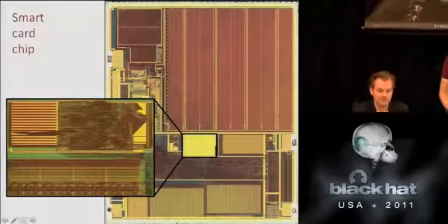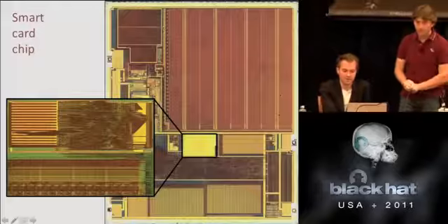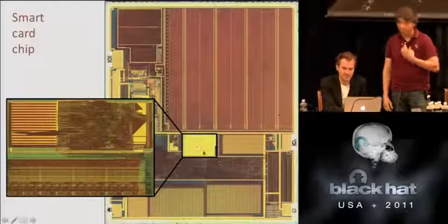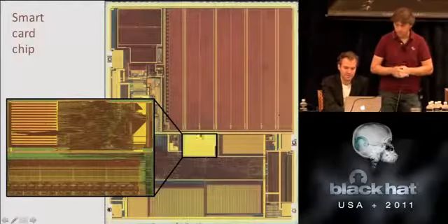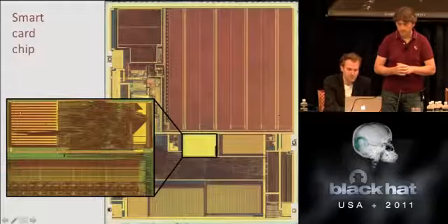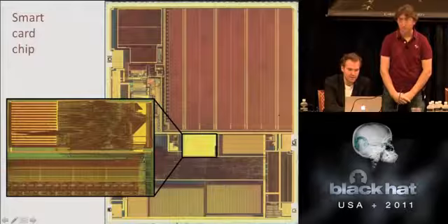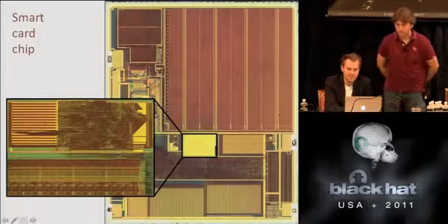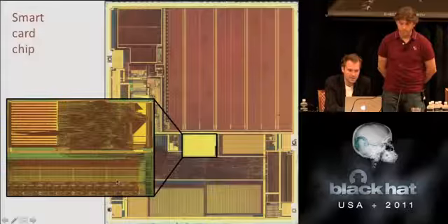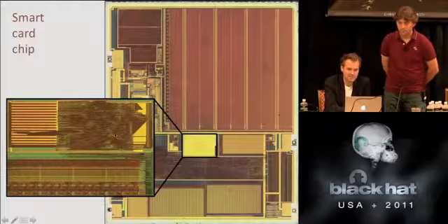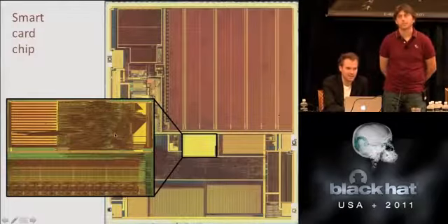All of these memories will talk on some common data bus that's probably routed throughout this big MMU maze in the middle, and then put into the CPU core from here. However, before hitting the actual CPU core, that's just this part up here, there's this block of logic, and this is a decryption function. So everything that's coming from the memories is encrypted until flowing through here, and only when it's jumping out of the decryption function, just before it's hitting the CPU core, is that the relevant data. That's the data you want, right?